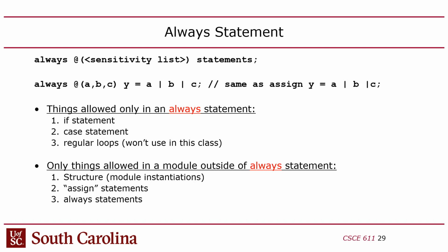So now you might say, well, okay, but you're just talking about the inputs, right? If the inputs change, the output may change. That's only true for combinational logic, logic with no memory. If you have sequential logic that has internal memory, like a flip-flop or a RAM, then the sensitivity list is the clock, basically. The outputs only change when you get a clock edge. Does that make sense? Generally speaking, these always statements are used for clocked logic.